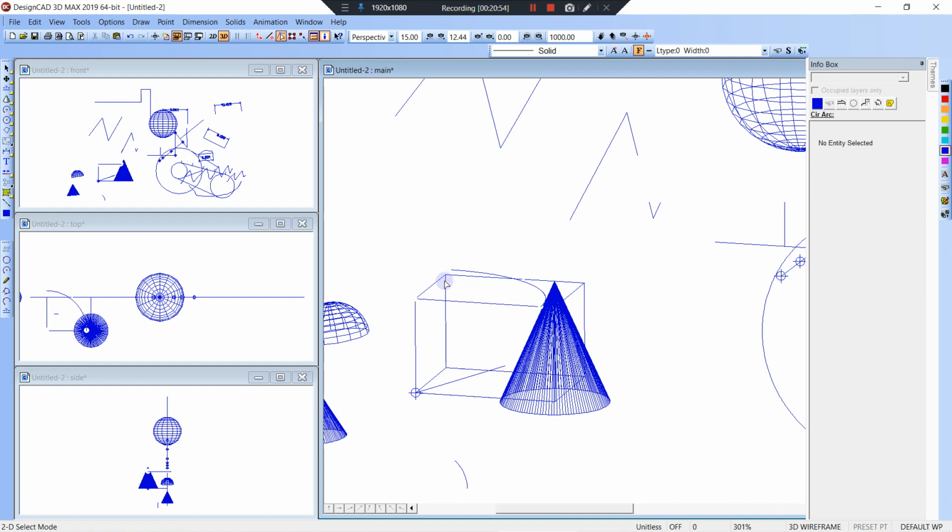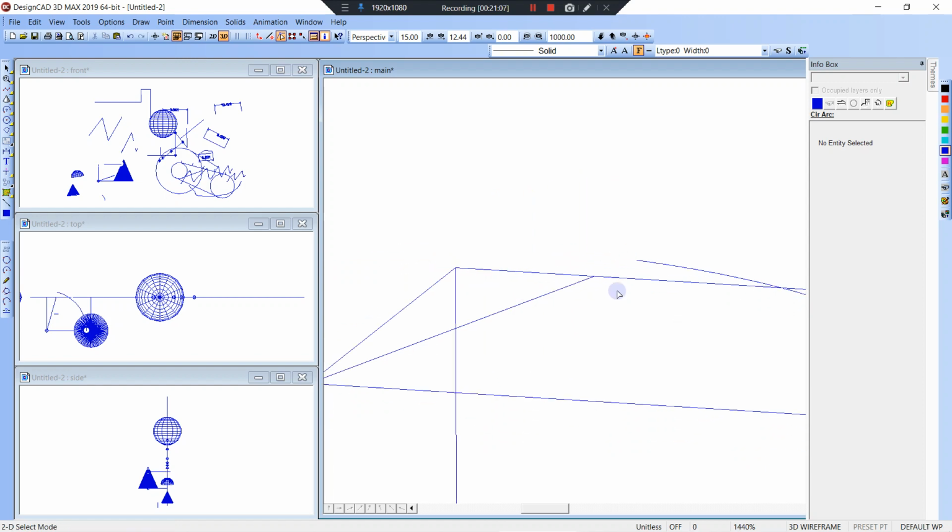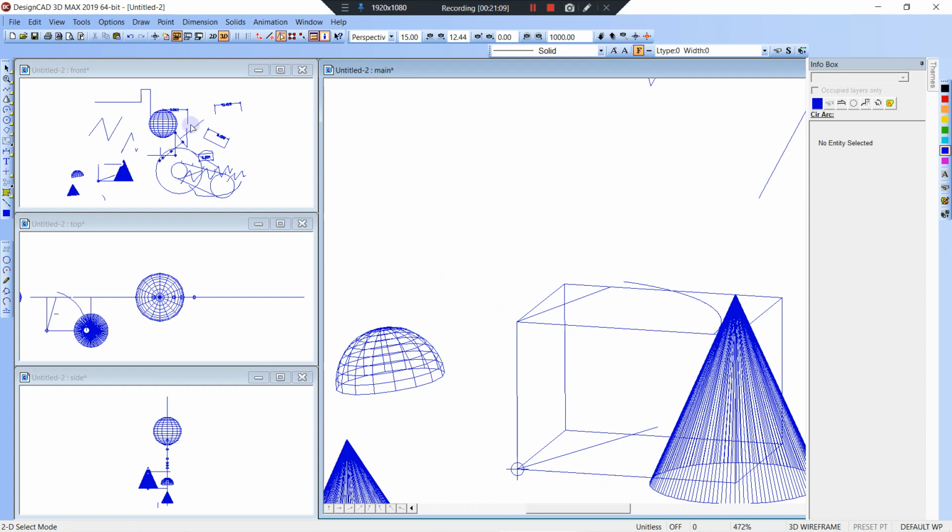And you can use trim, so if you had V, K, K, enter, you could trim it to that even though it's not touching. You could click that and it'll trim it if it's in the same plane. AutoCAD doesn't do that. I don't think you have to extend that. AutoCAD's funny. I have to use this program. Hardly ever use AutoCAD. Never use it unless I'm demonstrating. It does automated drawing very well and Lisp routines very well. All right, so there's a bunch of them. 3 points, very useful.